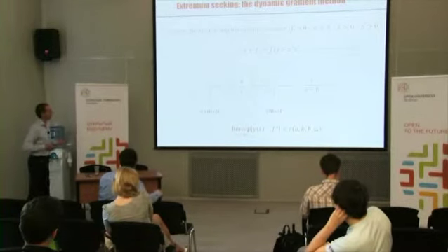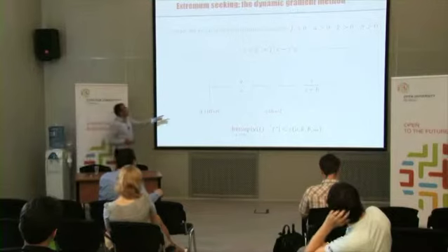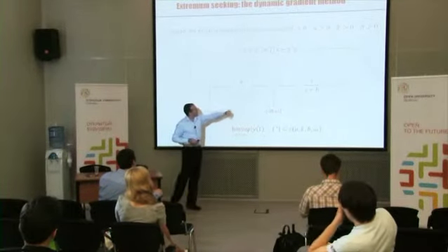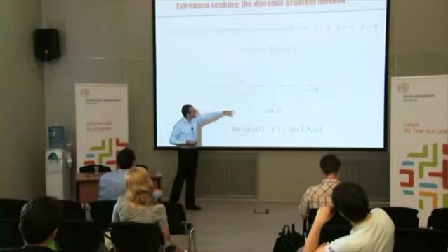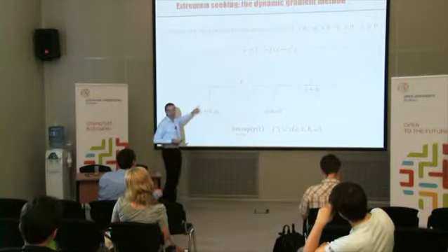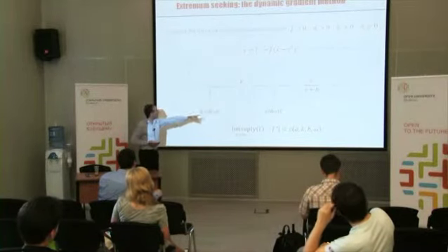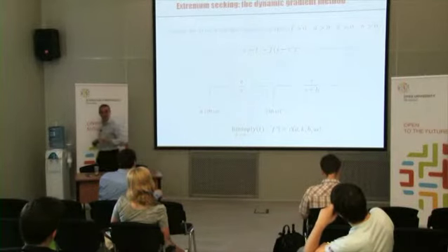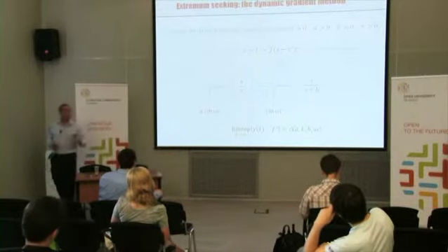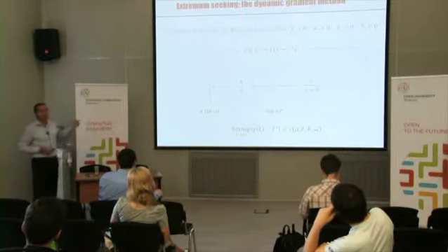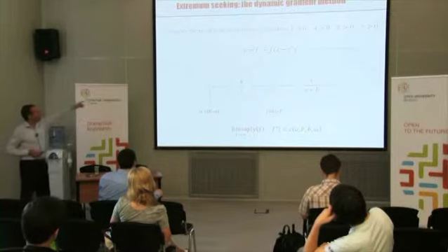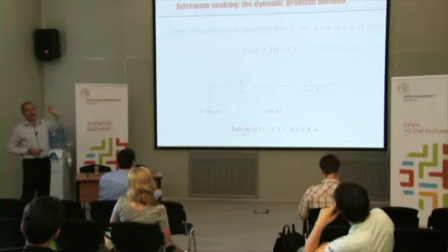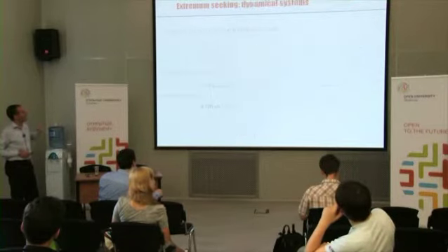in the negative direction. And you see that if we forget that signal for the time being, suppose this is a constant, you have a sine, you integrate, you have a cosine. This means that one is a derivative of the other. So we are considering the product of a signal with its derivative, which means that we are essentially implementing the gradient method, but we are implementing this online. And we are implementing this method with a closed loop system that doesn't know anything about the function. You don't need to know anything about the function.